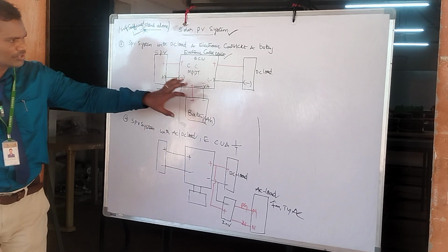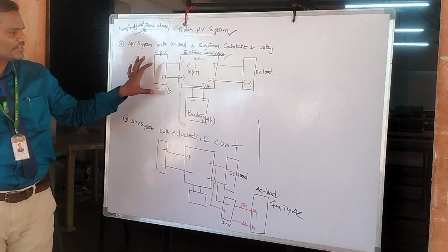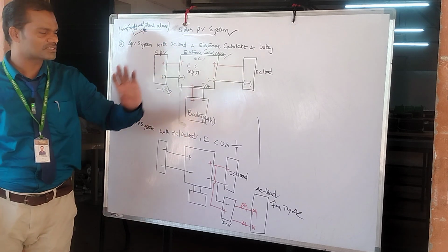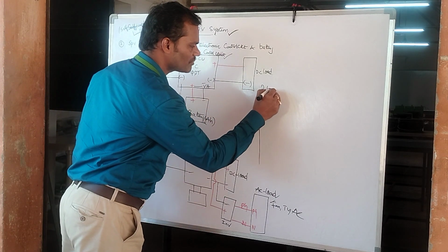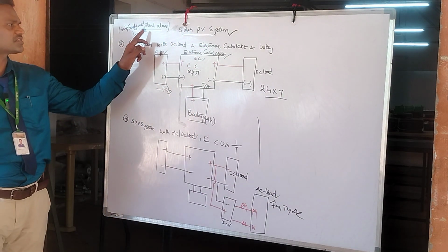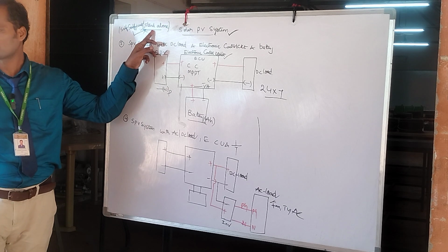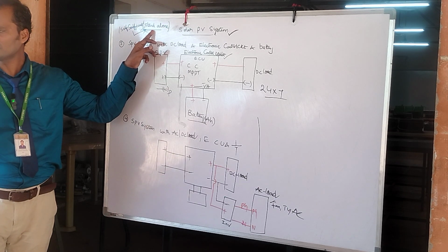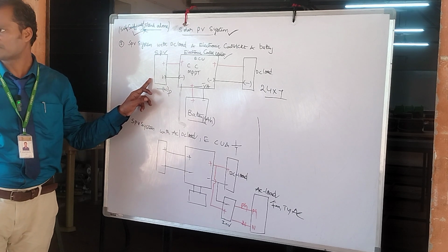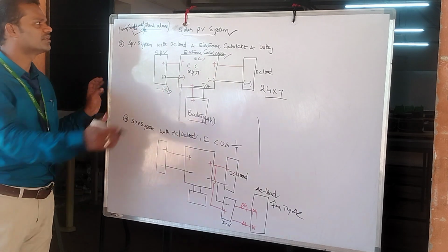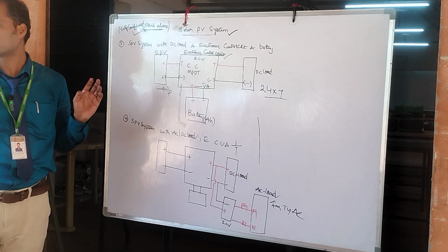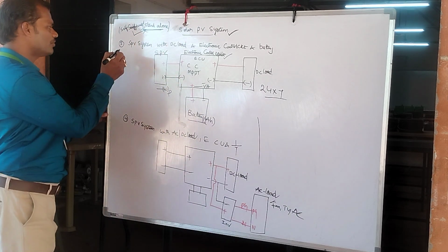So for this load, this is completely defined with a solar panel, and for backup it is designed with a battery. So 100% the load can run. If the system is designed to run for 24 hours, then those sort of systems are called standalone systems. They are not dependent upon any other source of energy, they are self-sufficient with what they have. Therefore those sort of systems are called a standalone solar PV system. Under this classification we are going to discuss today about